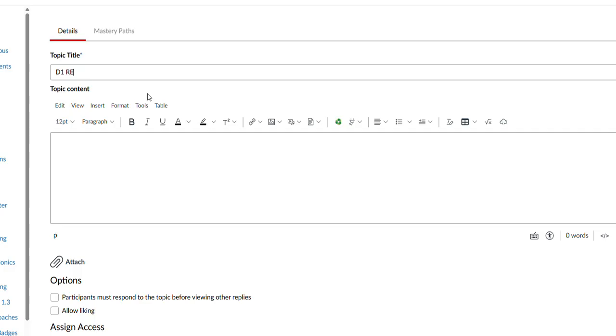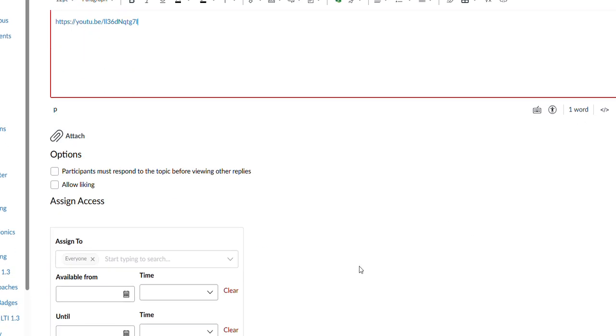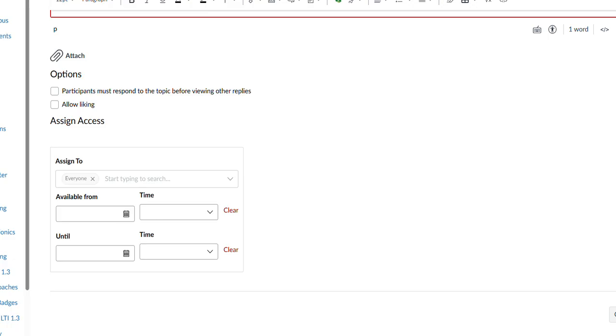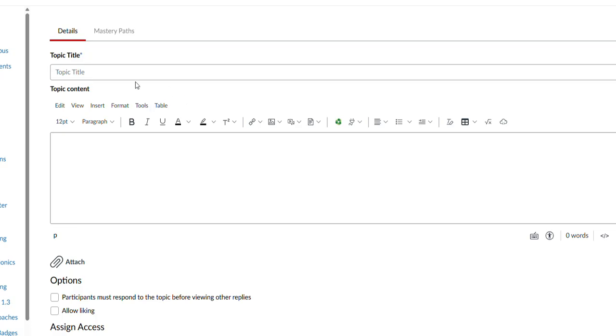I'll just name this the shim, just so you guys can identify what's what. I built this right on the 0, 0 axis, so I can work on the 0, 0. You guys would build your plane, do that same kind of stuff I did earlier. I'm going to make this my in-work object. And it's not the in-work object because I got to double click to get into the shim. Now I'll try and open that and make this my in-work object.